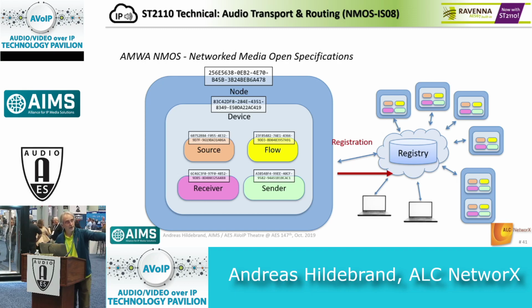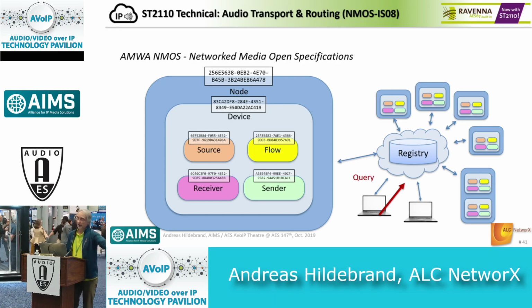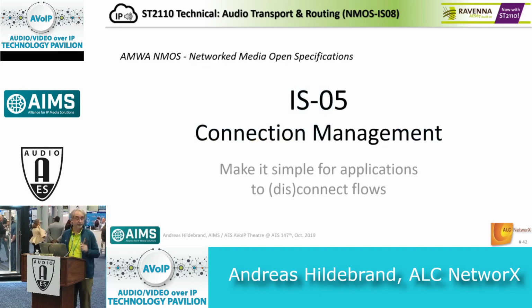Once all these devices register their resources into the registry, of course the control systems can query the registry and know what's on the network. And all the devices have to report any change. They also have keep-alive mechanisms. So once a device is disconnected, it will be removed from the registry, either deliberately or automatically. If the timeout is not respected, there's a timeout detection and the registry removes it from the system. So at any point in time, any state change, any resource is known, is registered in the registry service and can be queried by any interested instance on the network. That's IS-04.